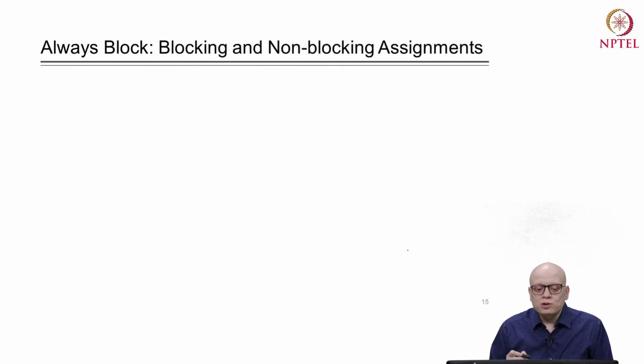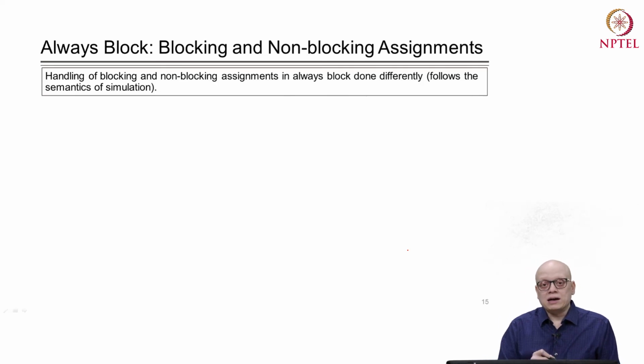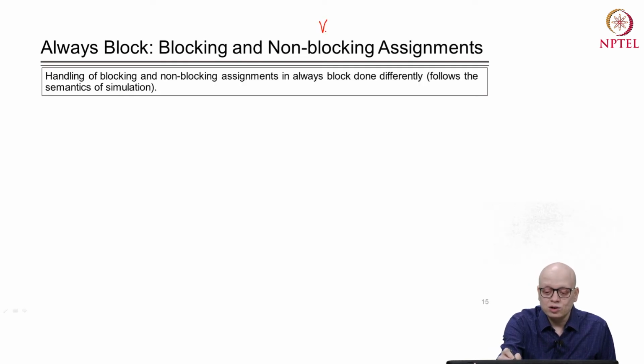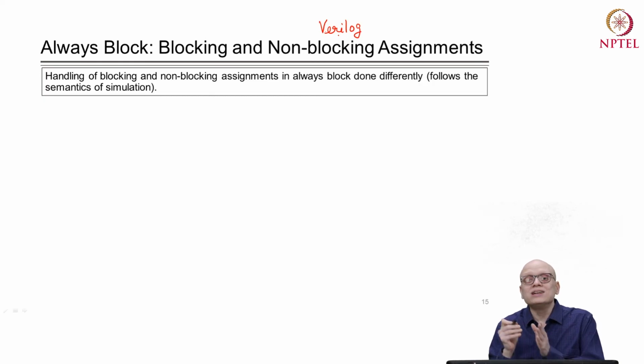Now, the always block can be synthesized in different ways depending on whether we are assigning a signal in a blocking manner or non-blocking manner. Okay. So, let us take an example and understand it. Another important point that should be noted is that the Verilog language as such was invented for the primary purpose of simulation or verification, right. You might remember that the word Verilog was derived from verification and logic, right. So, the initial purpose why Verilog was invented was for verification using simulation.